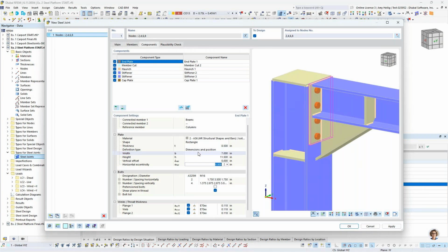So although it's bringing in these components from the library, we're most likely always going to need to make geometry changes unless we have identical members as what the library option does. So for this one, again, making changes to that end plate, this looks quite a bit better. So our bolts are going to be A325, and we're going to modify this to 1/2 inch diameter.